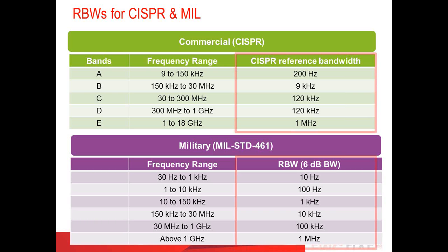Okay, so in summary, use as narrow a resolution bandwidth as you can, but remember, for compliance measurements, they call out very specific resolution bandwidths. Probably a better choice is to use as little input attenuation as possible and use either the internal preamp or an external preamp.